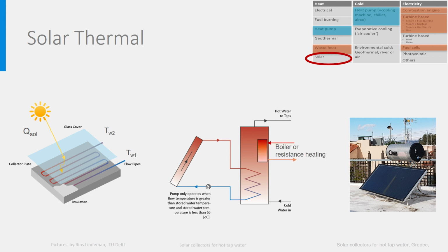In colder countries, such a solar boiler is even combined with additional heating by either a combustion or electrical boiler. There are many ways to improve the efficiency of the simple solar collectors. For instance, vacuum collectors have much higher efficiency. Concentrating collectors concentrate the solar radiation on the water pipe. It collects this way radiation that would otherwise fall at another place and can concentrate the radiation up to 100 times. Very high powers can be achieved this way.